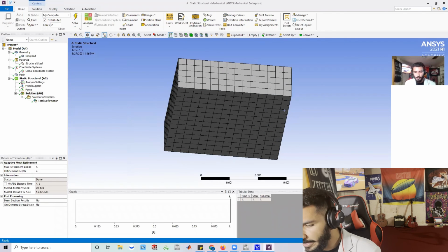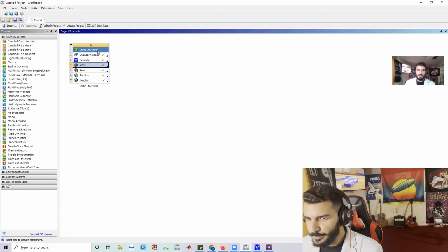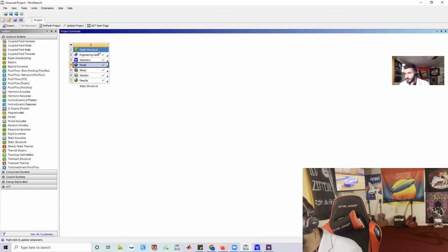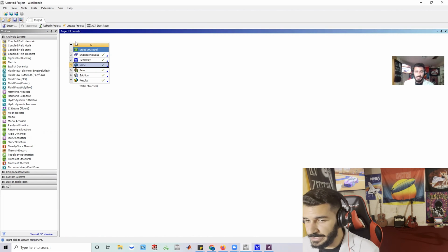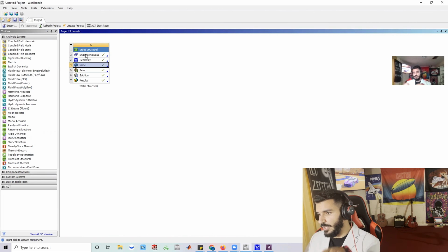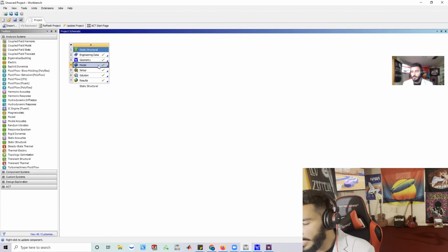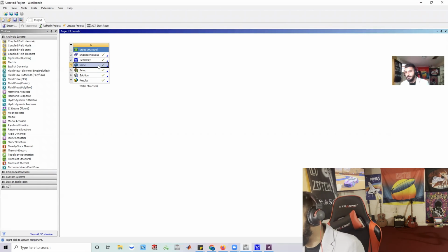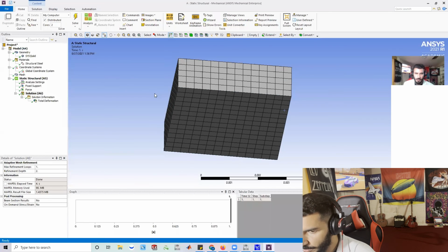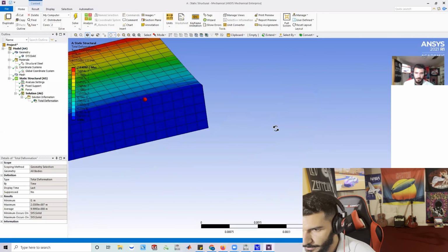So again, going back to that Workbench, the thought process was we first defined what physics we're interested in, in this case, mechanics, statics, things that do not move. We then chose the kind of material, in this case, steel. And then we designed something with that steel. We made a box made of steel. And then in the actual model, we told it, okay, this is what we would like to happen. We gave a scenario that, based on the physics that's pretty defined, we were curious about. And then we click solve, and then bam, this was the result.